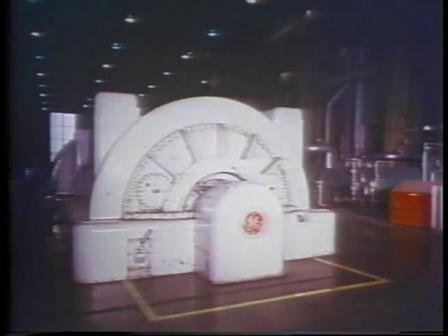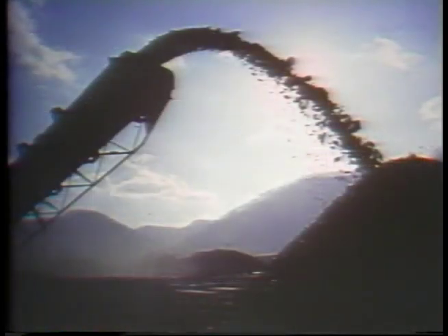We now know the amount of energy in each pound of coal, and we know how much energy is produced each hour of generator operation at full load. If we assume that the unit is 100% efficient, we can make a rough calculation of the amount of fuel that's needed to generate 26,550,000,000 foot-pounds of energy.